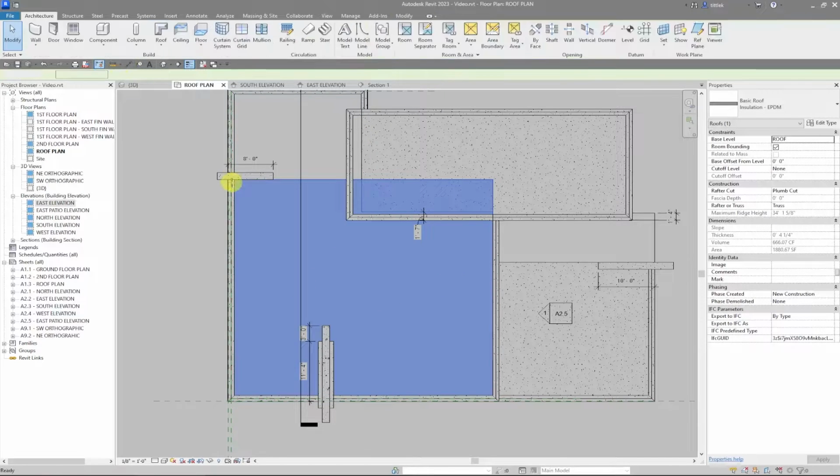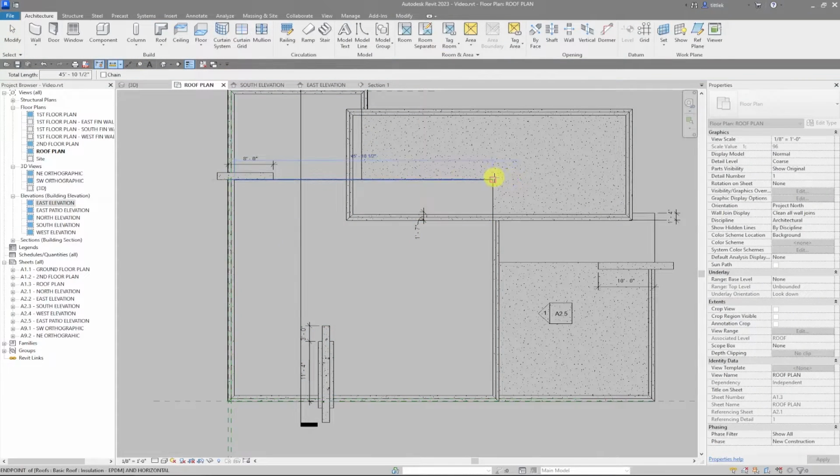If we measure this horizontally, we get 45 feet 10.5, and if we measure it vertically, we get 40 feet. So this is the longer dimension. So we want to make sure that we have a 1/4 inch per foot slope for the longer dimension, and that will ensure that our shorter dimension will be more than a 1/4 inch per foot. So I'm going to take 45 feet 10 and divide it by 2, because I only have to slope halfway to the center of this.